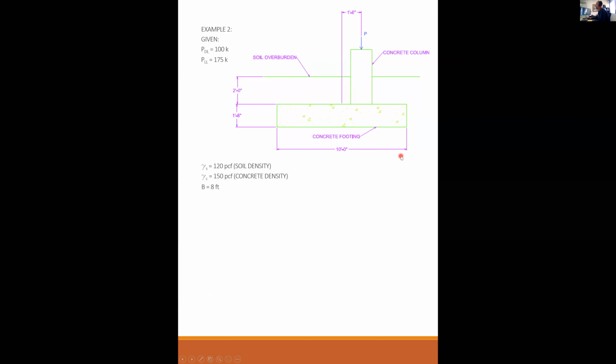The depth of the footing is 8 feet. The length of the footing as shown is 10 feet. Other dimensions are as given in the illustration. The allowable soil pressure is still 4,000 PSF. Required: is the footing as presented adequate for soil pressure?